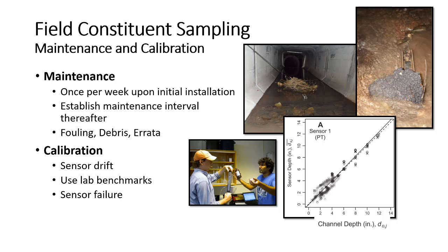Some of the other water quality constituents are more complicated though. The water quality sonde will come with some sort of a standard that you can compare your sensor's measurements to, the lab standard, and try to adjust accordingly. But in any case, this is also a component of trying to make sure that your system is working correctly. And I think once you get the hang of doing it, you get in a routine, it's really not that difficult, but learning how the calibration works and learning how to adjust the sensor. Sometimes the way that the computer interacts with the sensor, I've used programs before that do that, and it's like, I don't even understand how this works, right? You have to know some command line scripting to make the adjustments, and it's complicated.